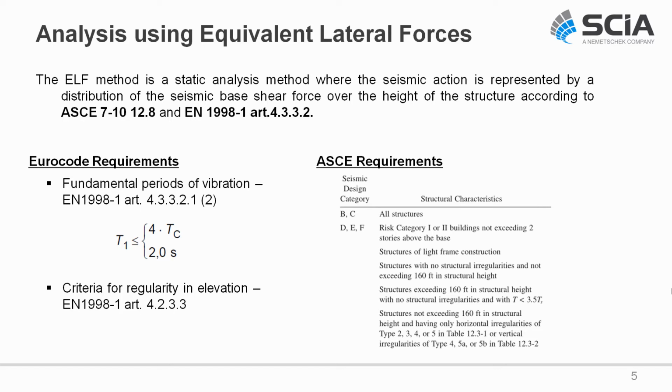According to Eurocode 8, some criteria need to be met in order to use this method. The first one is regarding the fundamental period of the building according to Article 4.3.3.2.1, and the other criteria should be regularity in elevation according to Eurocode 8 Article 4.2.3.3. We can also see here the ASCE requirements for using the ELF method.